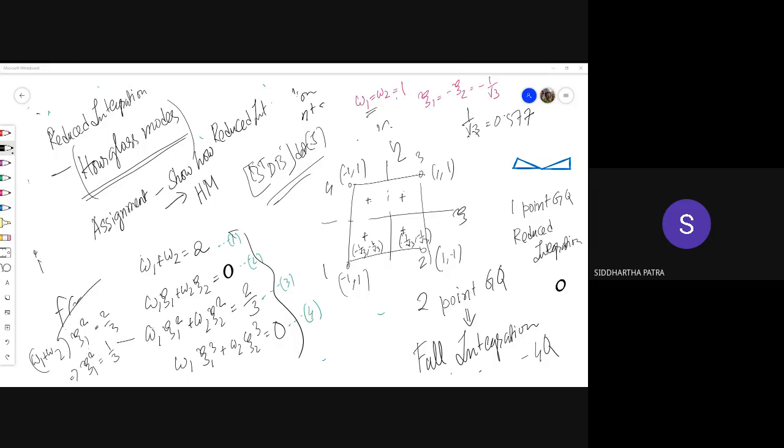It's always that. If the computational cost didn't matter, you would be refining the mesh infinitely. Then we would not be calling it finite element method. We would be calling it infinitesimally small element method. We could have been doing that, but we cannot because the computational cost does matter. If I refine the mesh so much that the elements are infinitesimally small, I'll get the exact solution for any problem. If I could do that, I would do that. But the computational cost is the biggest concern.